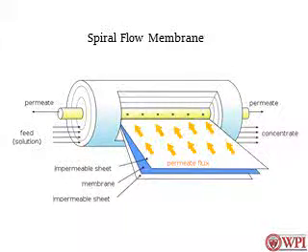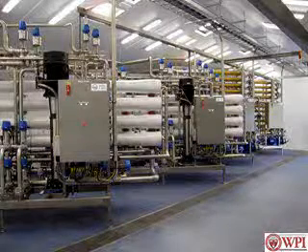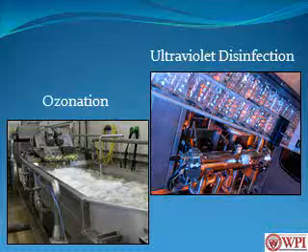A newer and emerging treatment technology is using a membrane application which captures and retains the dissolved solids or other constituents. Typically, the main issue with membranes is clogging as organic waste builds up on the membrane surface. As a result, new membrane applications have been designed, such as centrifugal and vibrational systems to limit clogging. Also, stainless steel and ceramic materials as membranes improve cleanability and the reuse of the membrane.